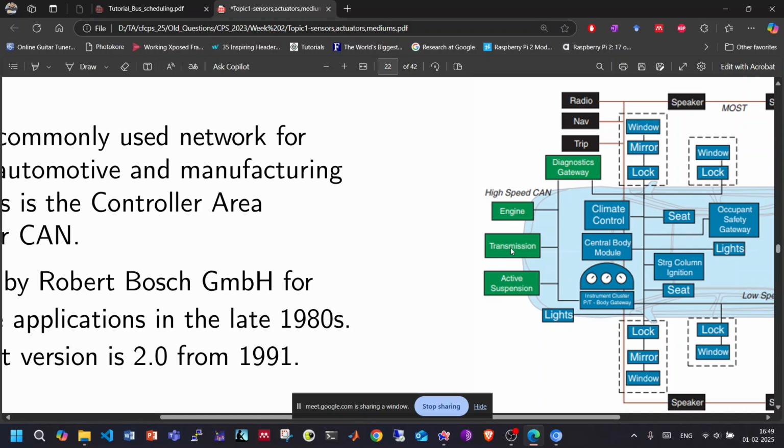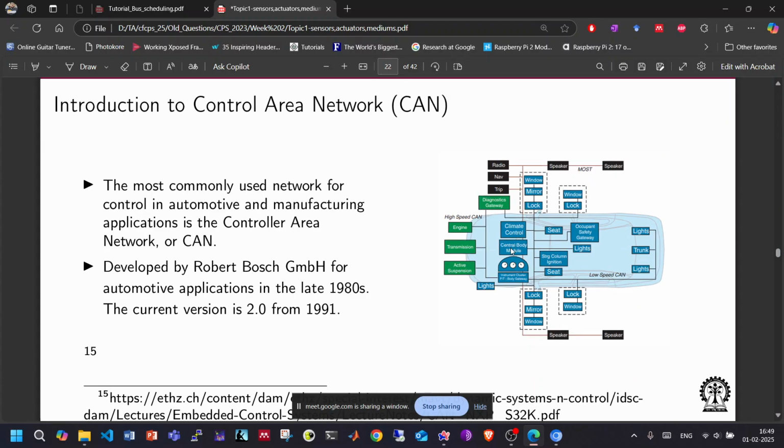So now we will see fewer situations where both should be transmitted, but only one will be transmitted and one will be delayed. Obviously, the one that is preferred, that is having a lower ID, will be transmitted first. The other one will wait until the first one transmits. Then only the control operation that needed both of the data will be done. Make sense?